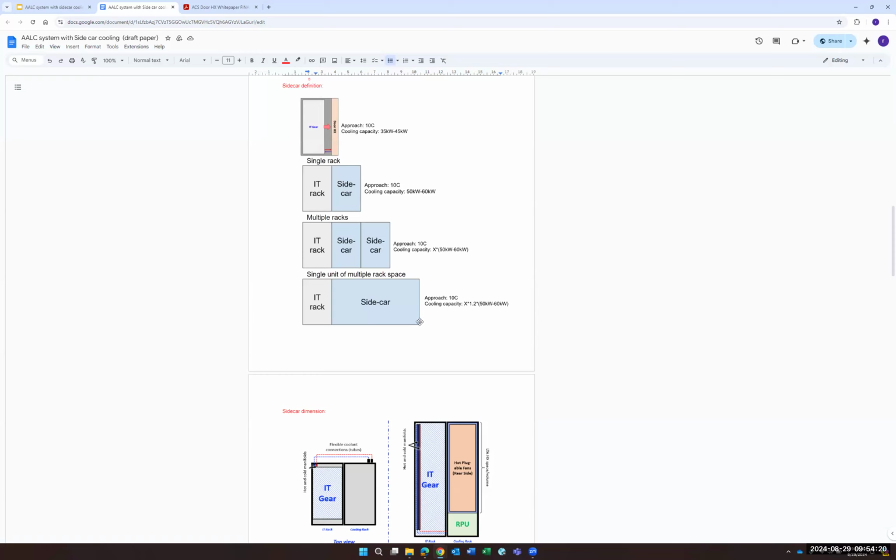The two single wide sidecars are going to have 4 pumps in them. It could have 4 or more, or even 3 should work. 3 could work if you go to, let's say, an AC pump instead of a DC pump. But if you did a double wide sidecar, you'd probably put 2 even larger pumps in it. Even a single sidecar right now will have, I think, 3 pumps. At least 3 pumps, yes, to have n+1 redundancy. And ours have 2.